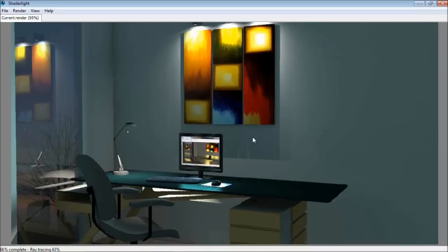This is actually a limitation in IBL lighting, and it's purely because the sun, as I mentioned right at the beginning, the sun in SketchUp is an infinitely small point of light, whereas on an IBL the sun is a given size, so it does spread the light. So the shadow's intensity can be a little bit lighter. But this is something we are looking at, different techniques of how we can change different ways of working with IBL, and we've got a good team of guys here, so we're confident we'll see something on that.